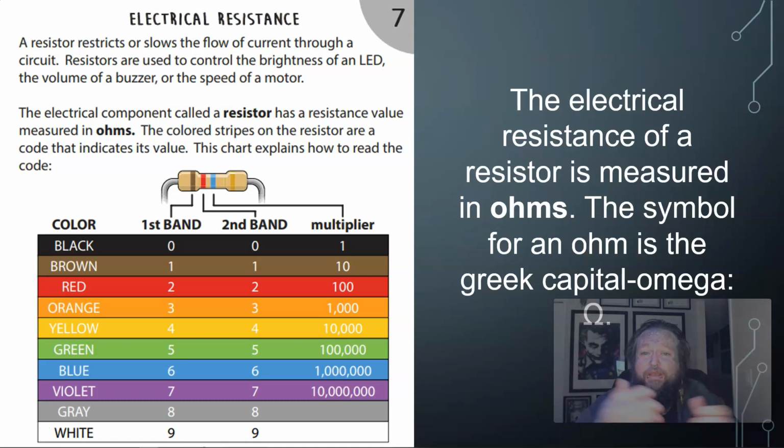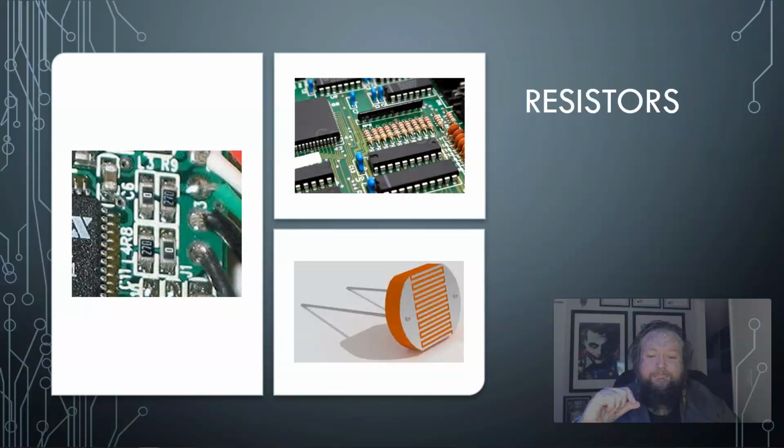You want to be careful, because you could plug a resistor in, and if it's too high, the light's going to be really dim, it's going to cause problems, and it's not what we wanted. Or if it's too low and it doesn't restrict the current level, we could have problems on the other side of the circuit. So you want to follow roughly the resistance. Most of the kits will tell you the bands and the colors and what it looks like. Or if you've taken them all out and you're not sure, you have to go back and look at the orientation from one side to the other, so the gold band on one, reading from here downwards, list those, and then you can figure out the proper ohms. But sometimes in the kits it's hard to read those colors.